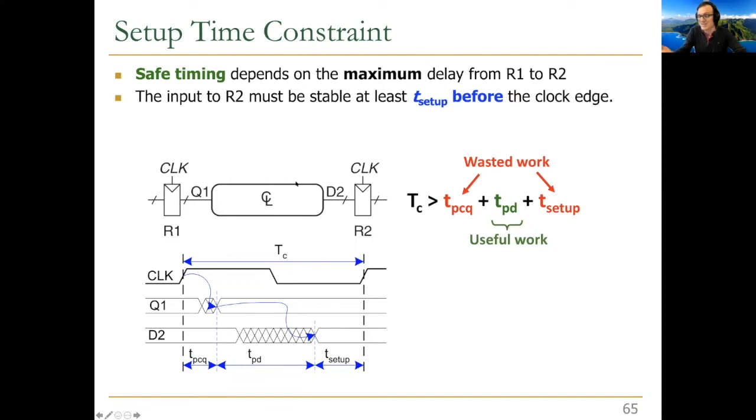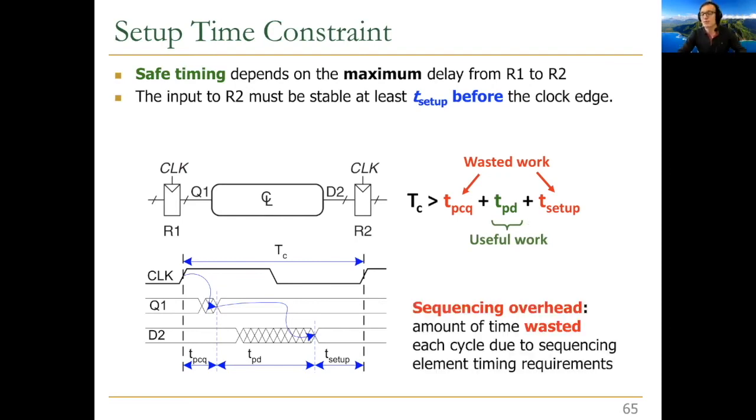That's the idea, and that's how we can pipeline circuits, as we discussed. What I just told you is a form of pipelining. You don't do the full addition in 1 cycle. You do half of it here, latch the data value, and do the other half in the next clock cycle. If you didn't understand it, don't worry about it. We'll talk about pipelining. But you have some control over your TPD, depending on how you design your sequential system. So this was the sequencing overhead.